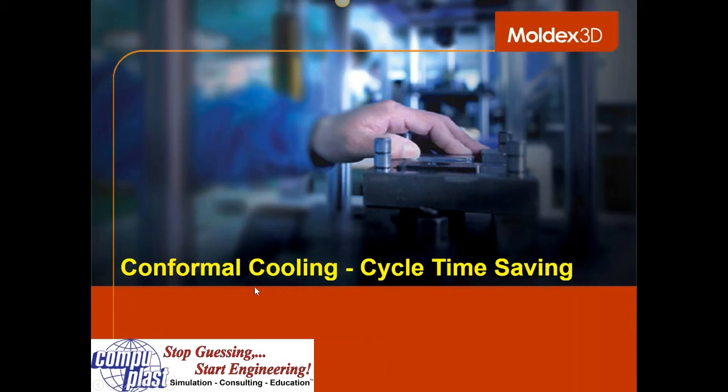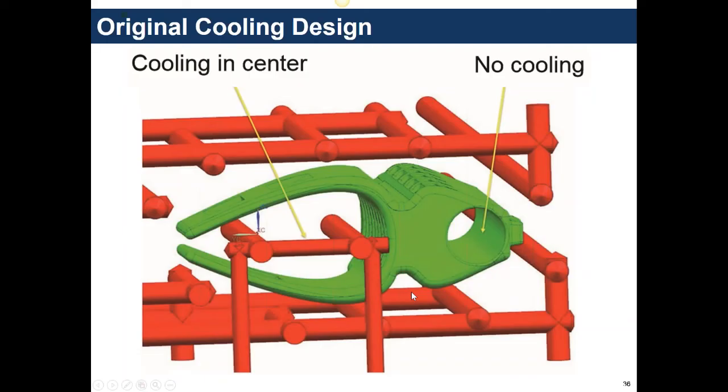Now this project was using conformal cooling, and the customer wanted to reduce his cycle time. So we asked them to send us the original model of what they were running. They did not like the cycle time they had there, so we looked at the cooling system. And here you can see they used a traditional cooling system by drilling channels in everywhere.